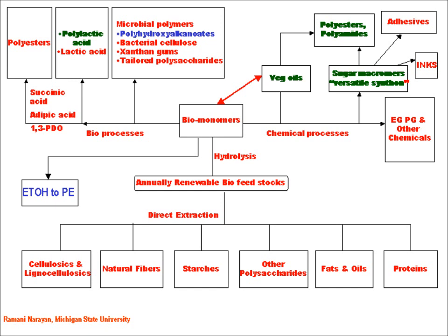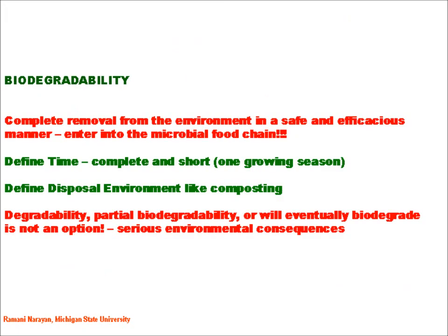So, you can make all these macromers, and the more important part I wanted to bring out to you here is the fact that recently Braskem announced making polyethylene from a biorenewable feedstock. So what you have there is converting sugarcane to ethanol, which then goes through the standard process, making ethylene out of ethanol, and then following traditional polyethylene. So you have a biopolyethylene feedstock over there. All right? So this is the potential and possibilities you have over there.